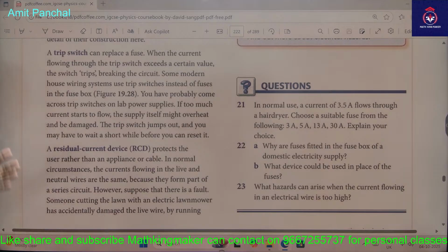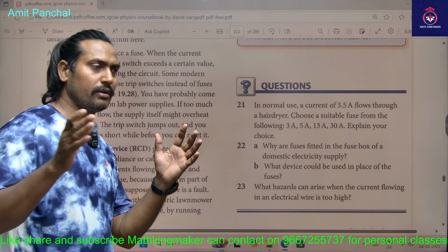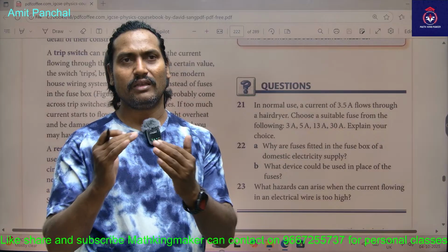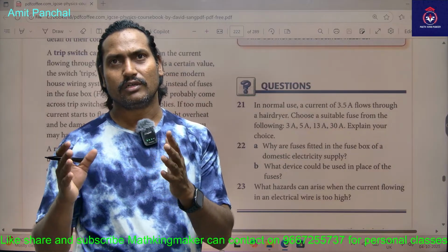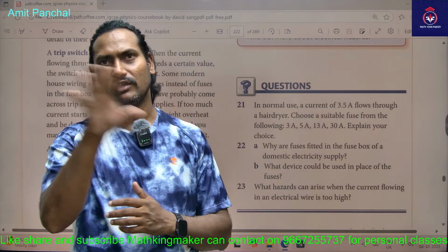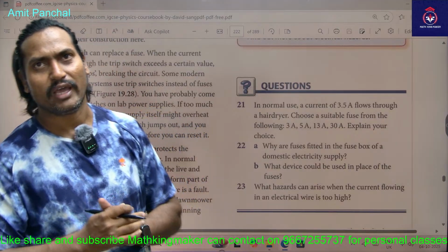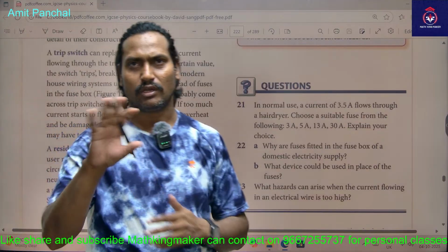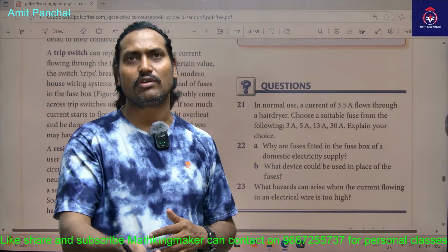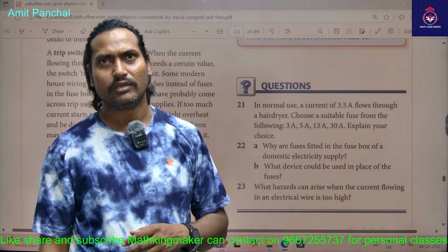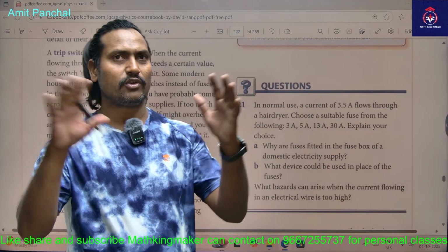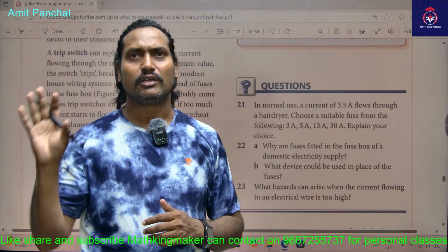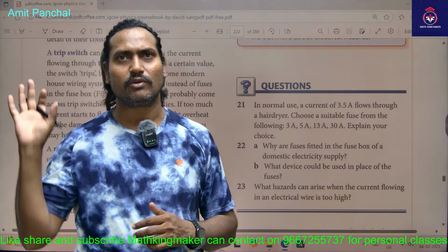So generally we don't have fuses in our main circuit board, the MCB. There is a panel outside the home, and in that all CBs and MCBs connections are there. So if somewhere there is excess supply or some circuit or some appliance has a short circuit, what will happen? That particular CB will trip off. Like for a room, you have 3 CBs and the fan is shorted. That particular CB will be tripping off.